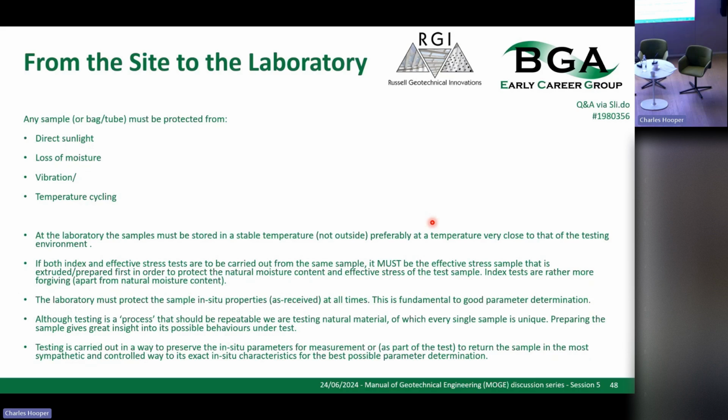And if we take it through part of its stress history and we approach its in situ stress point from the right direction, and rest it there so that it's in equilibrium, we will then be gaining the best parameters that we can get, and hopefully removed a little bit of the disturbance. We certainly can improve the sample. We may not be able to turn it into exactly what was in situ, but we'll get it to the best state that we possibly can.